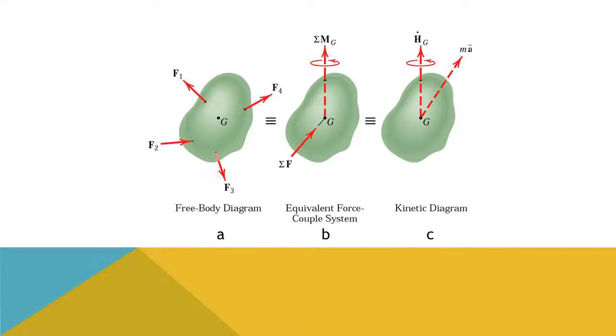By replacing the external forces by their equivalent force-couple system in which the resultant force acts through the mass center G, we may visualize the action of the forces and the corresponding dynamic response of the body.